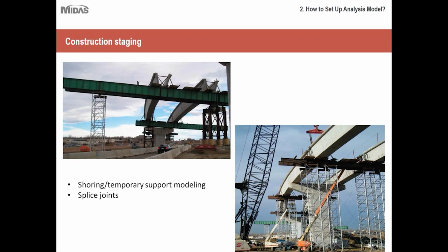So what are the challenges that engineers have to go through in this? First of all, the splice joints, their deformations and the camber, that is very critical to ensure the final layout of the bridge. So you have to model those supports at appropriate locations, and sometimes you have to assess the forces that are coming in the shoring member.